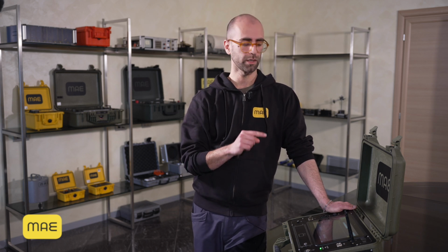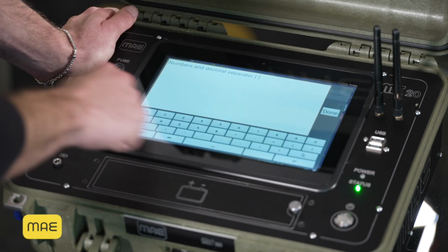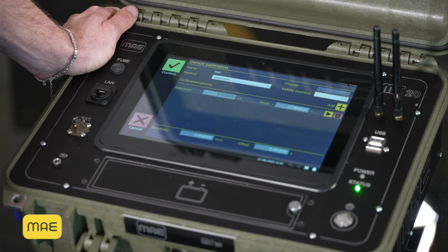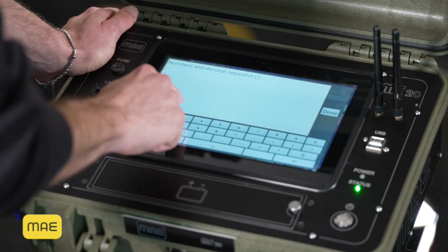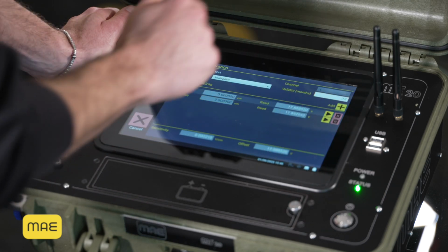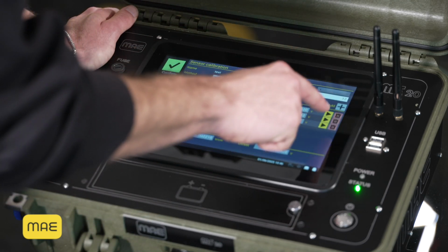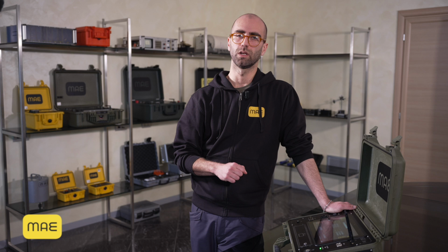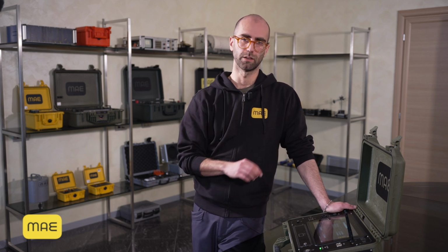For every calibration point, we click on Add. We select the reference point and we press play. We repeat the process for each reference point. In this example, we're using a 3-point calibration, but you can use any kind of point. At the end, the system will automatically give you the calibration parameter. This is a linear calibration.